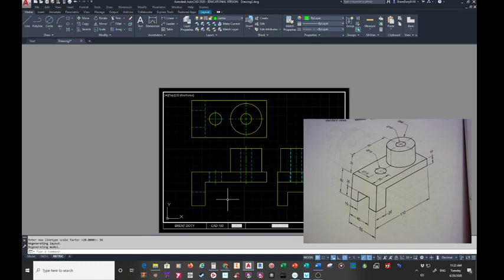Okay. So, see, what I'm worried about is I want to make sure that my shortest center line shows up right, and that my hidden lines are long enough to where you can tell that's what it is. And there's not a perfect line type scale. The perfect line type scale is, it looks good to you.